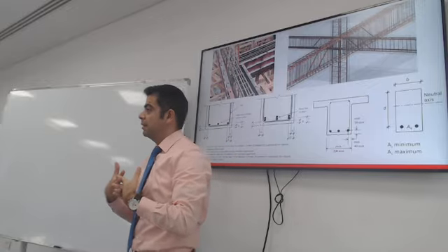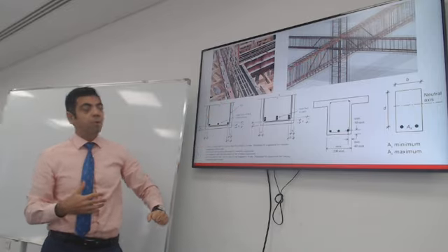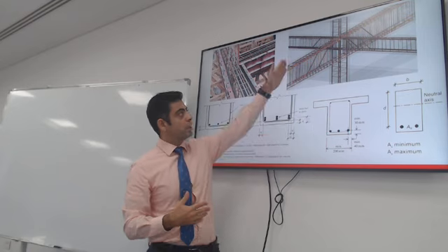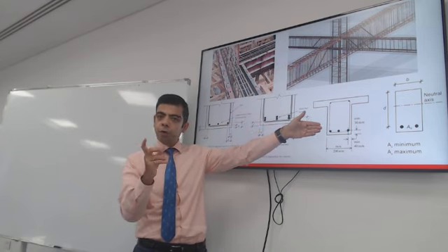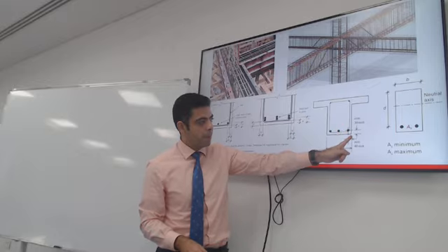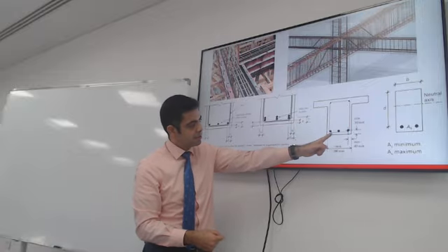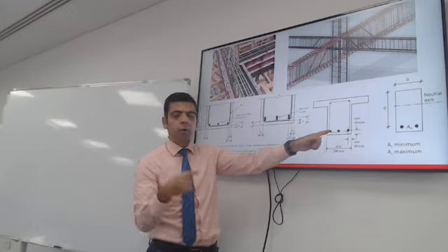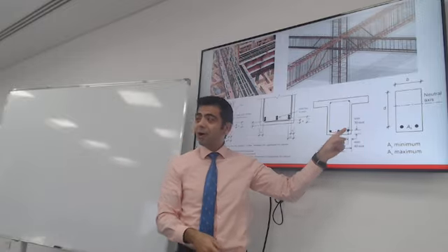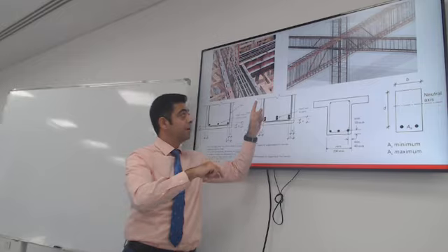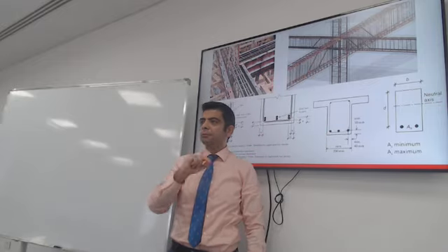Does that make sense? So if there is one thing I want you to understand from this slide, it is that when you take a cross section in a reinforced concrete beam, you expect to have a few things. There is the overall dimension or the overall width of the section, and inside it there is a stirrup with longitudinal bars going into the page. So each black dot, this is a bar. This is a bar that is running along the beam. When you take a cross section, it will look like a black dot.